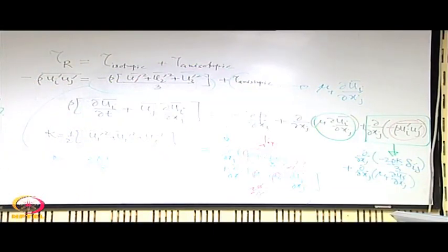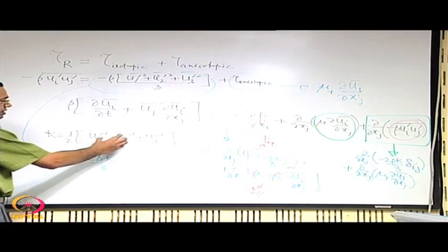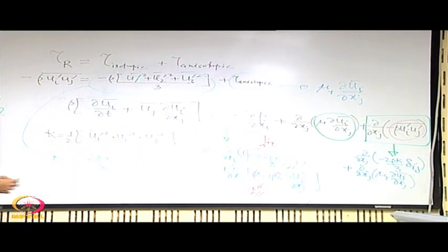In this context, we will just remember that sometimes this fluctuation kinetic energy is expressed as a non-dimensional parameter in terms of the kinetic energy of the mean flow at the inlet of a pipe, for example.